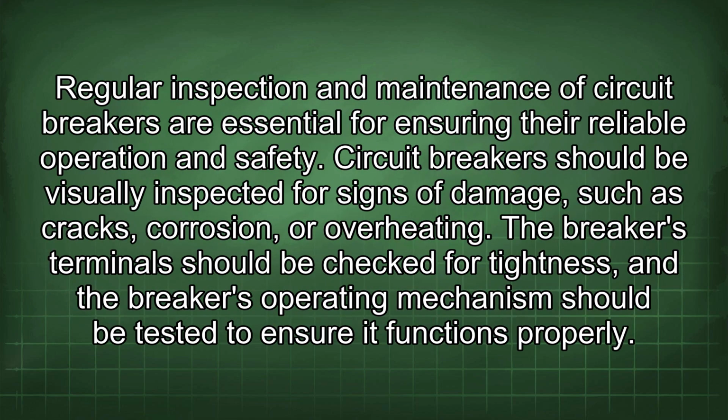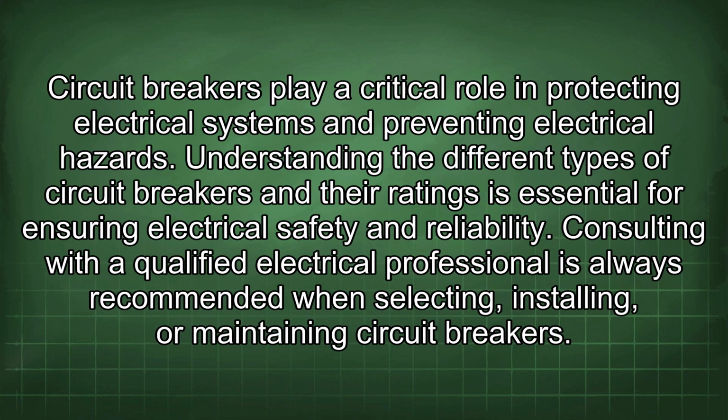Regular inspection and maintenance of circuit breakers are essential for ensuring their reliable operation and safety. Circuit breakers should be visually inspected for signs of damage, such as cracks, corrosion, or overheating. The breaker's terminals should be checked for tightness, and the breaker's operating mechanism should be tested to ensure it functions properly. Circuit breakers play a critical role in protecting electrical systems and preventing electrical hazards.